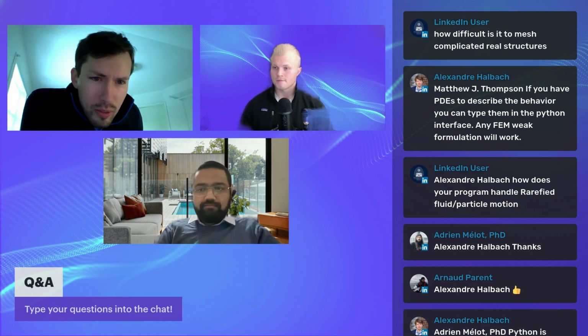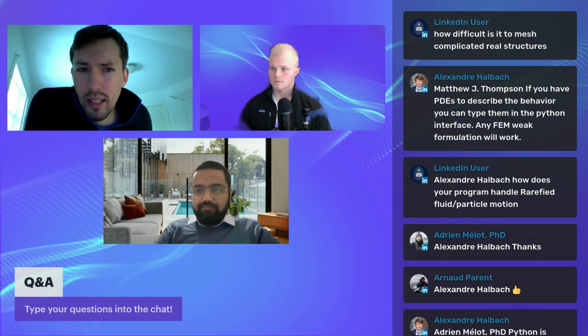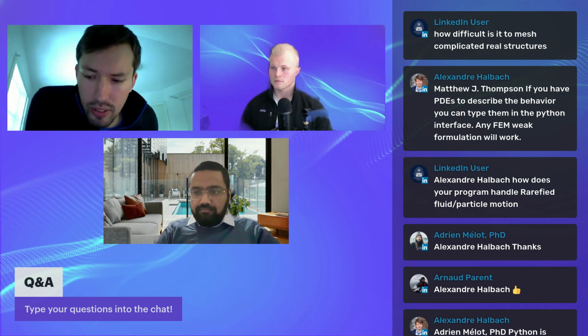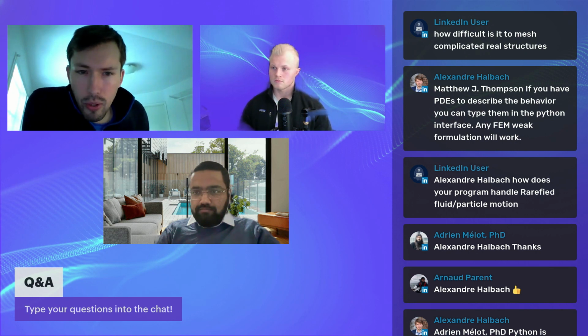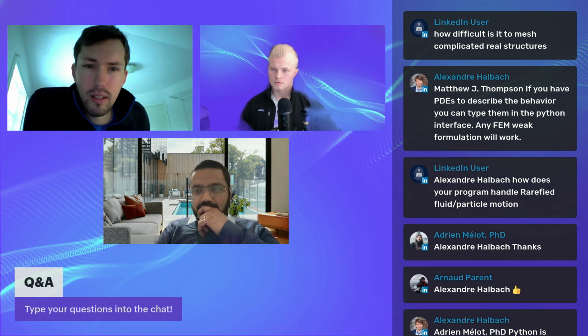I see. Jukka, how difficult is it to mesh complicated real structures? Well, it depends what you mean. If you mean thin layers with MEMS or complicated structures like big mechanical assemblies, we can deal with both. So you can import a step file or GDS files. And basically, if you have drill holes or fillets, we have a special measure that handles this really well. This is for the mechanical assembly side, so complicated geometries, yes, it's FEM, so any geometry works, and we mesh it with hexahedra, pyramids, prisms, and tetrahedra, so anything really works.